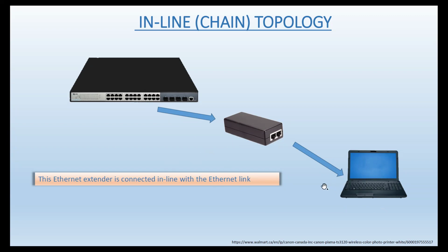So what I would do is put in one of those. You see, when we are testing the wires in the lab, it will be exactly the same tester. I would plug in the end of it to one end, and I'll go with my meter, plug it into the other end, press the test button, and check for the distance. Well, I'm not checking for the distance because the distance is going to be displayed on it, so I'm just going to read what the distance is.